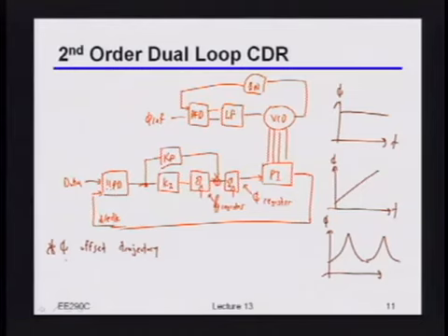Okay, so sometimes you're worried about some spur coming out of your chip. And if it has too much power spectral density, then the FCC gets unhappy or something like that. So sometimes what you'll do is indeed this spread spectrum type of technique, where you intentionally spread the energy of that clock out over a band of frequencies. Okay?